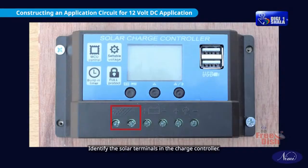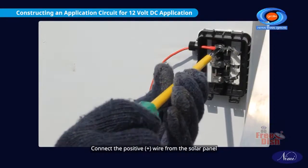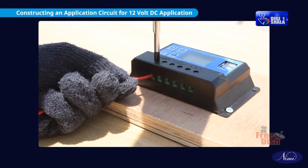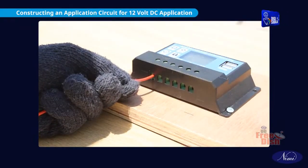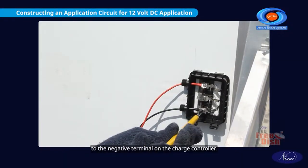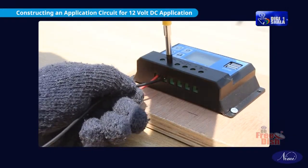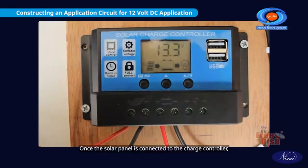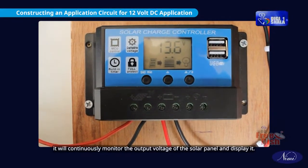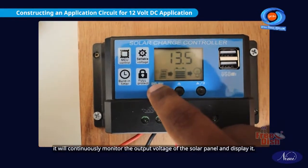Identify the solar terminals in the charge controller. Connect the positive wire from the solar panel to the positive terminal on the charge controller. Similarly, connect the negative wire from the solar panel to the negative terminal on the charge controller. Once the solar panel is connected to the charge controller, it will continuously monitor the output voltage of the solar panel and display it.